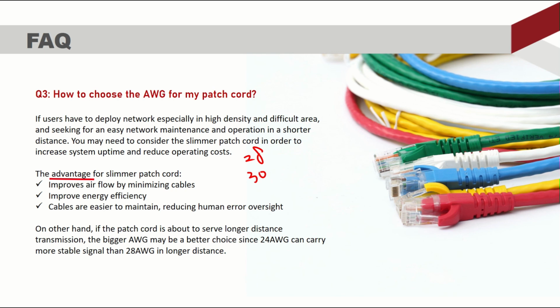But on the other hand, if the patch cord is going to serve a longer distance, we suggest you use a thicker cable like 24 gauge. It can carry a more stable signal than 28 gauge over the longer distance.